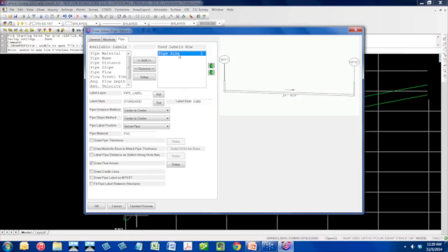The pipe size is all I'm showing here. Maybe I want to show the pipe material, the length of pipe, and maybe the pipe slope. If I pick Update Preview, you can see it just kind of pushes it all together here. We can reorder. So maybe I wanted to say, 10-inch or 12-inch RCP, or maybe, let's put distance up front. So I'm doing the up arrow. So we'll do the pipe distance or pipe length.